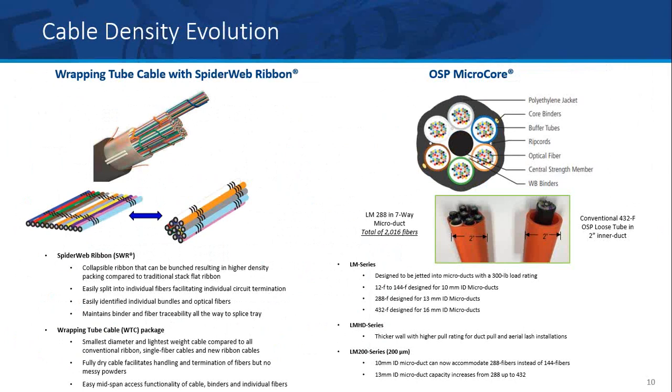And blow in one cable. Then you need to expand it, blow in another, blow in another. And you can see how you can really expand your fiber count, expand your capability, and also defer your costs. So you have the pathway in place, and if you use a standard 2-inch conduit, as in the picture example there, you push or pull in a 432 fiber in a conventional 2-inch interduct.